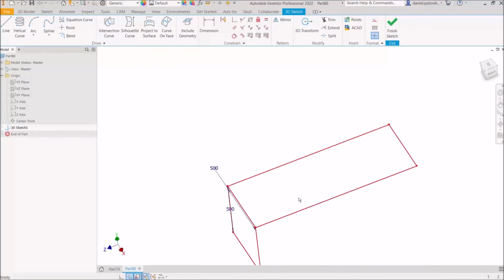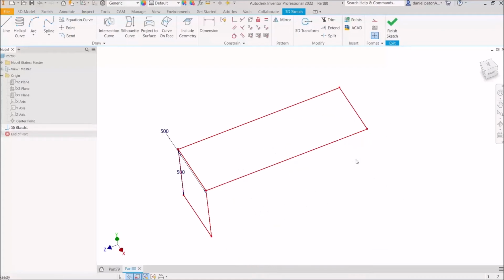Okay, so you can manipulate the 3D sketches, but I'm going to show you how we can rather create this using 2D sketches and then fill in the additional geometry using 3D. The reason why this is better, in my opinion, is because it's a lot easier and a lot quicker to define some 2D profiles, and it gives you a good anchoring point for your 3D geometry to link to.